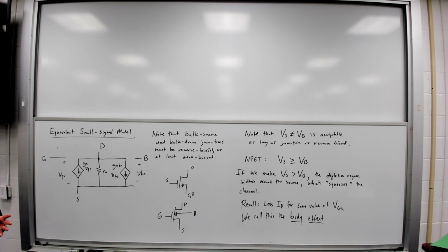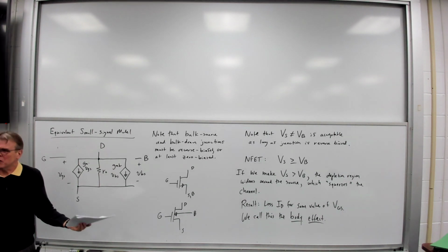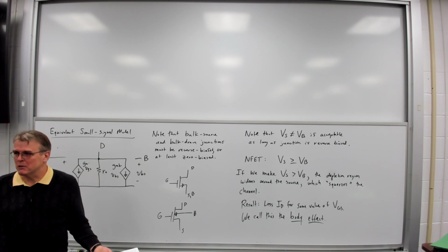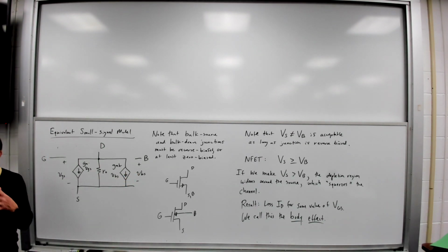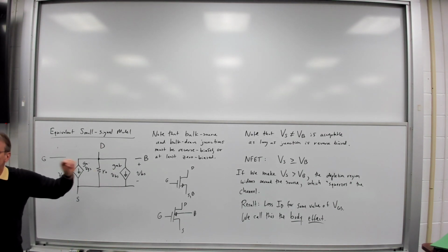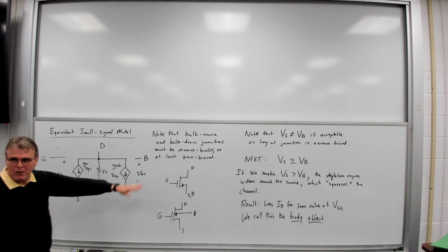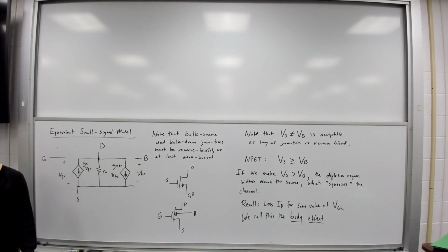So it is not common, but it is not unheard of. So that's why I wanted to bring this up. Now, we're not normally going to be dealing with the body effect. I don't think any of the homework problems really ask you much about the body effect. But I just wanted you guys to be aware of it, because in more advanced circuit designs, high-performance circuits, you will occasionally see body-driven amplifier circuits, where they are separating the bulk and the source terminals, and they're actually operating them as amplifiers.